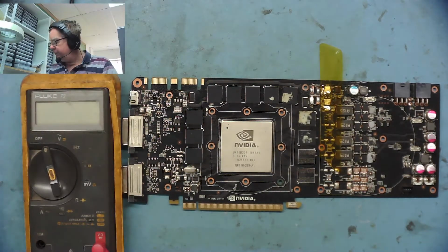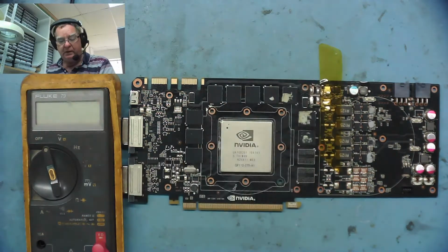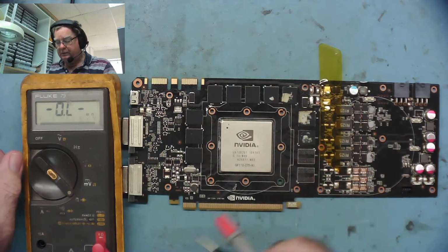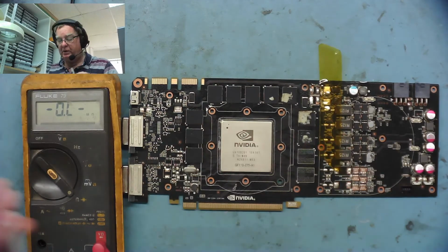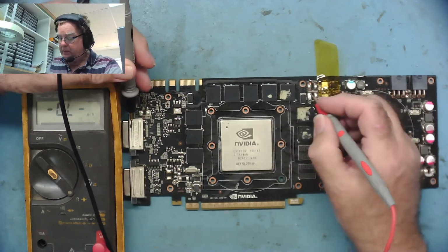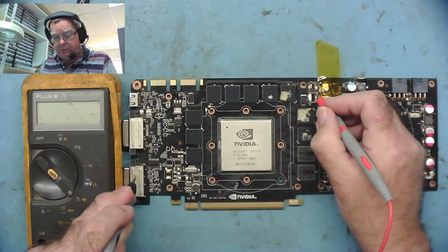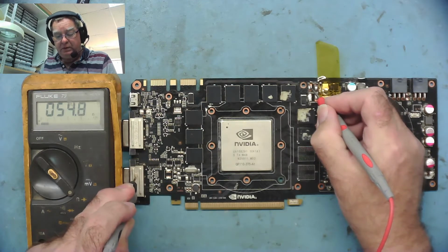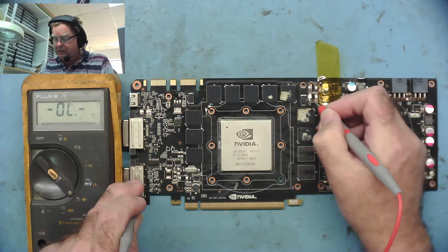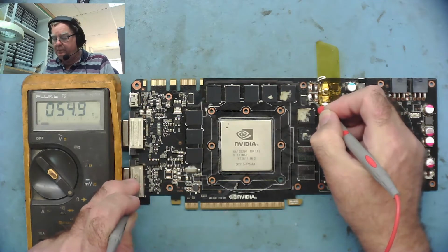Okay, so that's cool enough now. Let's have a look. Still a bit warm, but you can touch it, it's fine. So what we want to have a look at now is the resistance to ground either side of where these coils were, because this for certain will tell us which side the low resistance was. The one we really want to know is the GPU and the RAM. Do we still have 9 ohms? No, we don't. I'd expected nearer to 100, but that isn't unreasonable, I think, for a RAM supply.